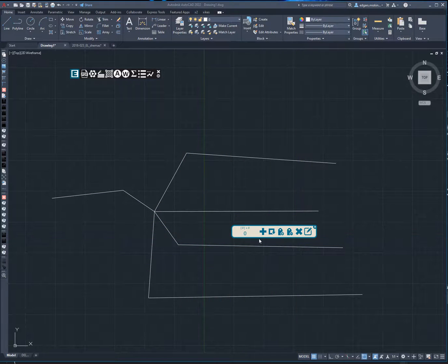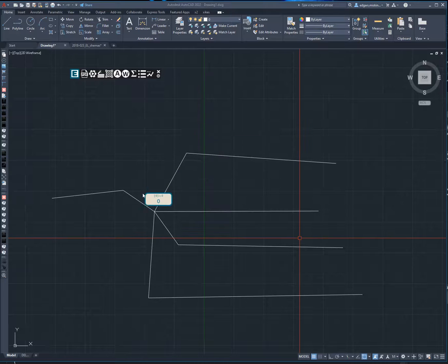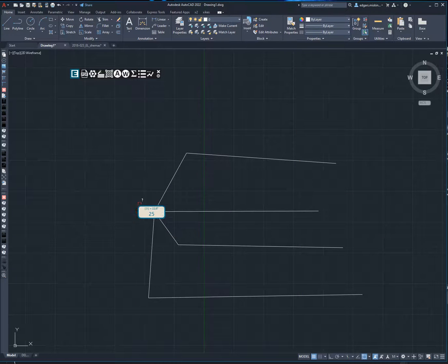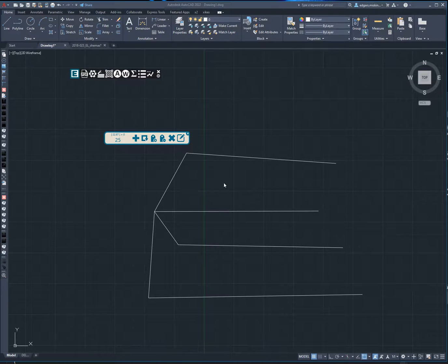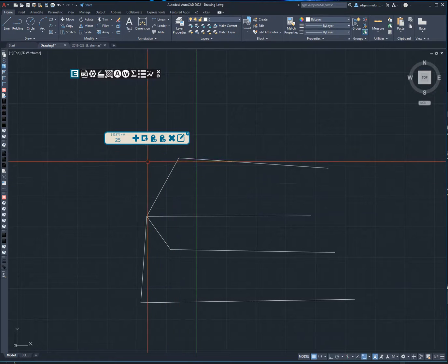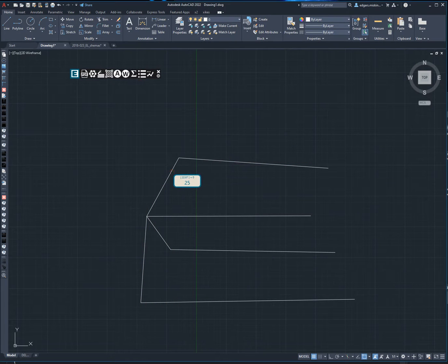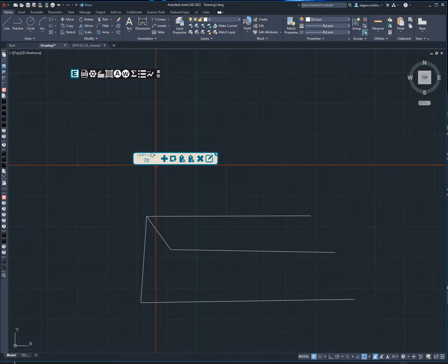So let's say this just resets everything. Let's start a new measurement. Let's now press escape. Now this is this part. Now I can press this button, and the length of this previous segment is saved as a static addition to all the next segments that I will measure. So now if I measure this one, as you can already see in the little square, it shows the calculation. This is the total sum of this previous segment and this additional segment.